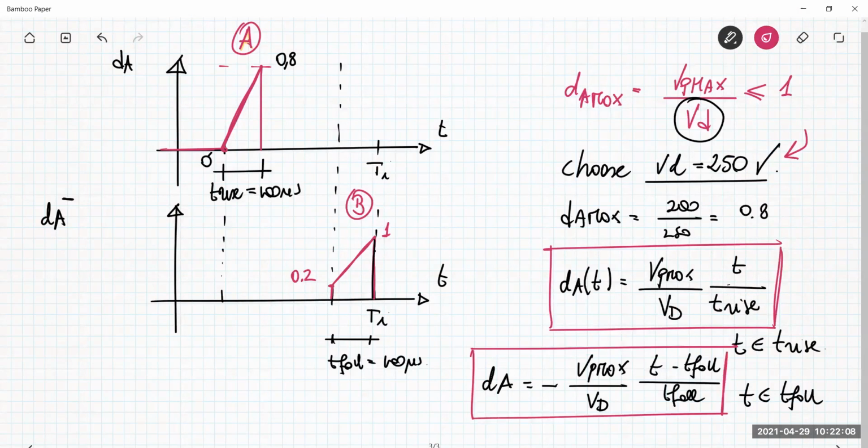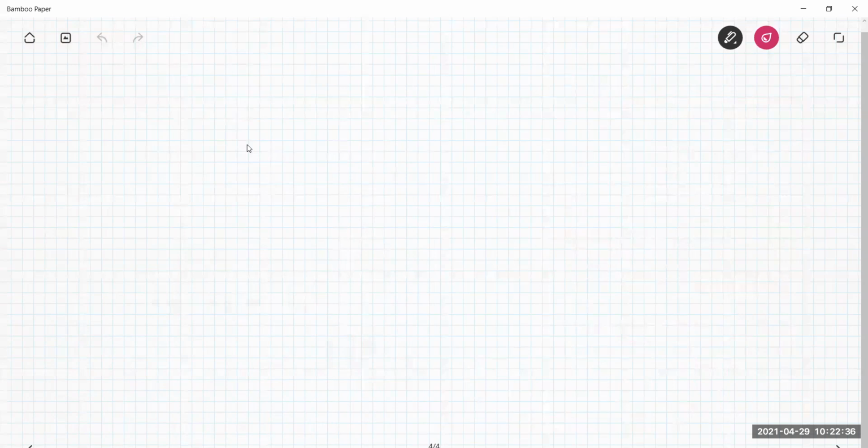So these are the two expressions of the duty cycle that you need for my specific strategy, which I repeat myself: the transistor TA plus is only operated on and off during the rise and then always off, and TA minus is only operated during the boost phase, the phase B, and otherwise it is always open.